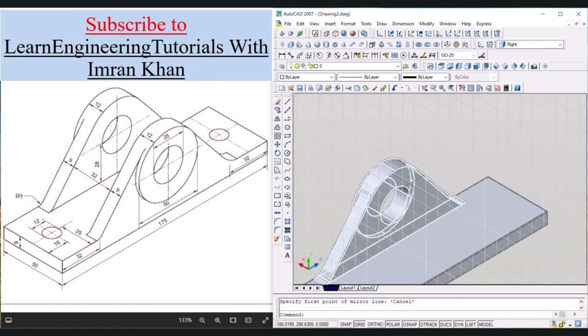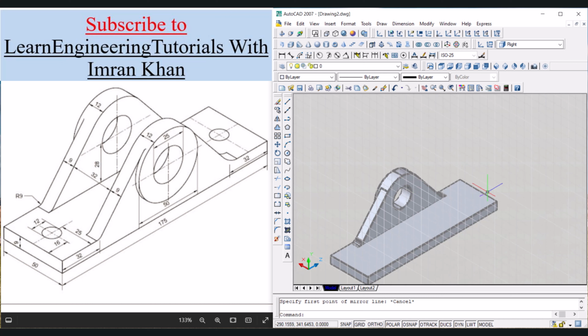Now we have to mirror this object across this axis, which passes through the midpoint of this surface. So let us draw a line. Click on line, select this midpoint, and then select the other midpoint. Press escape.